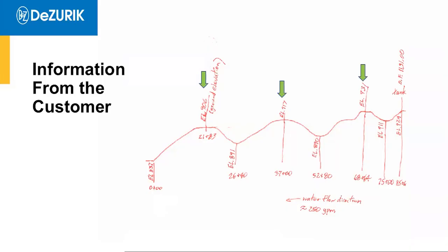And so as I looked at it, okay, so the green arrows show the high points. I recorded those. On the furthest left green one there, you can see the elevation is 906 feet. And you can also see that the station distance is 2183. That's what I need. I have the same information for the other points. Now, also likewise, I have the low points, which help with my calculations. And I have the distances, I have the elevation. So I more or less have what I need.